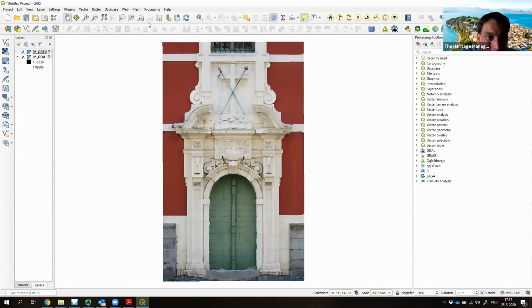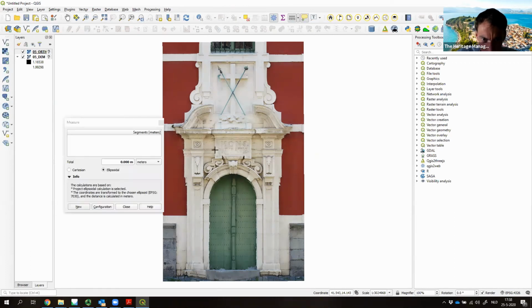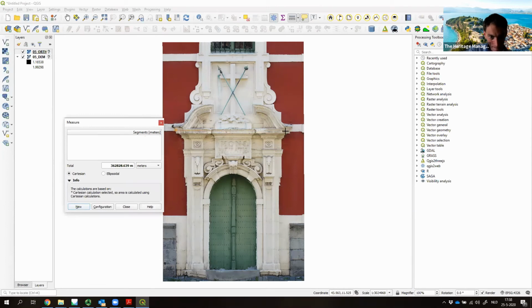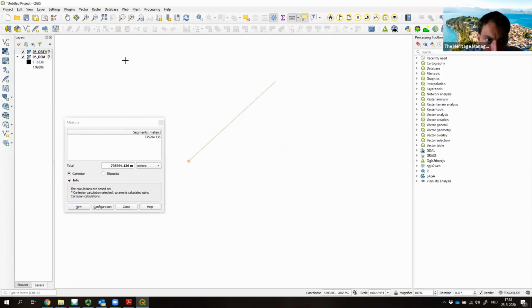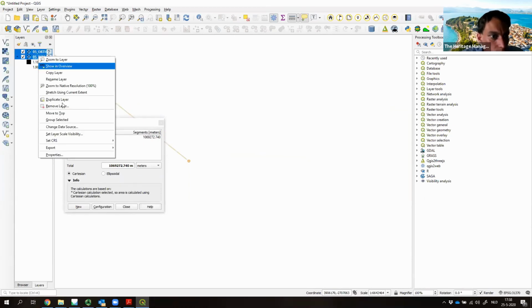And that assumes, and that's very important to mention here, that if I measure a distance using QGIS, the distance from here to here is actually a distance calculated in meters, but derived from degrees. So it actually means that we are going around the globe a couple of times. So this definitely doesn't make sense. We should better take a metric coordinate reference system to start with.